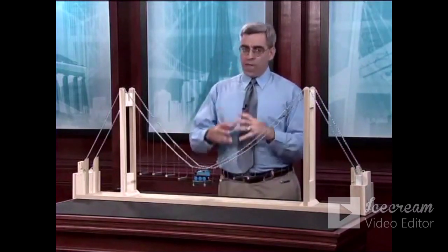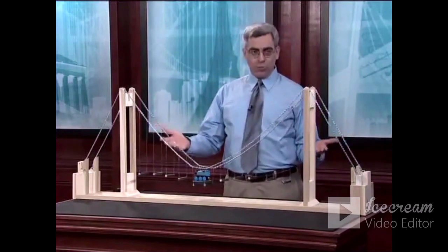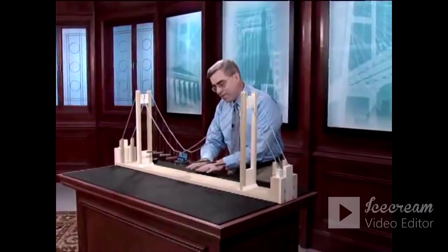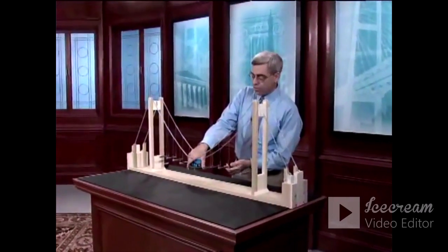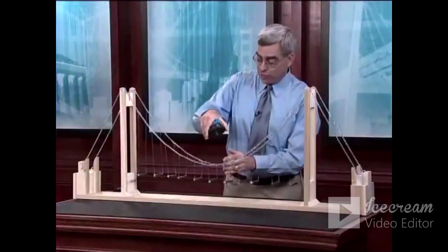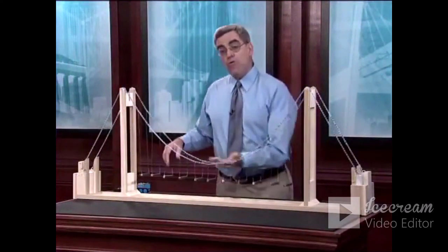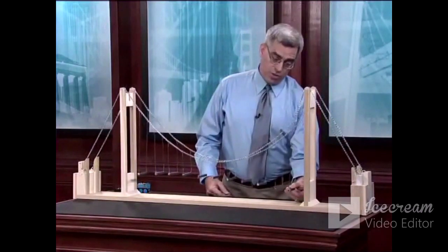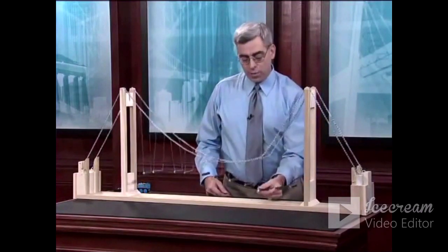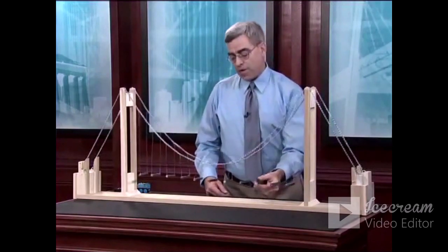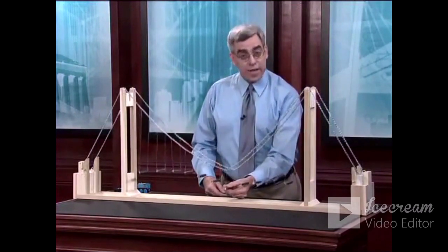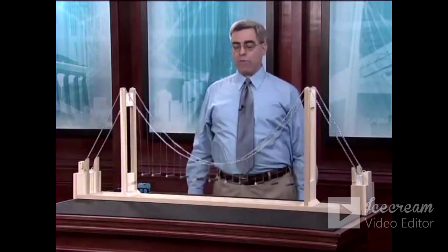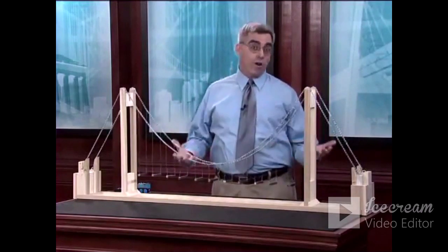Well, that's all well and good, but if this is a functional suspension bridge, we have a problem, because that sort of distortion in the cable also causes a significant downward deflection of the deck that the vehicles are driving across. So imagine if you're the occupant or driver of a vehicle that's moving from one side of the bridge to the other. When the vehicle's located here, the cable distorts into this shape. As it moves to this location, the cable distorts again, but into a different shape. By the time it gets out to midspan, it's distorted into yet another shape again. And all the while, the bridge is undulating and undergoing all these crazy deformations. Clearly, it's not practical as a functional structure.